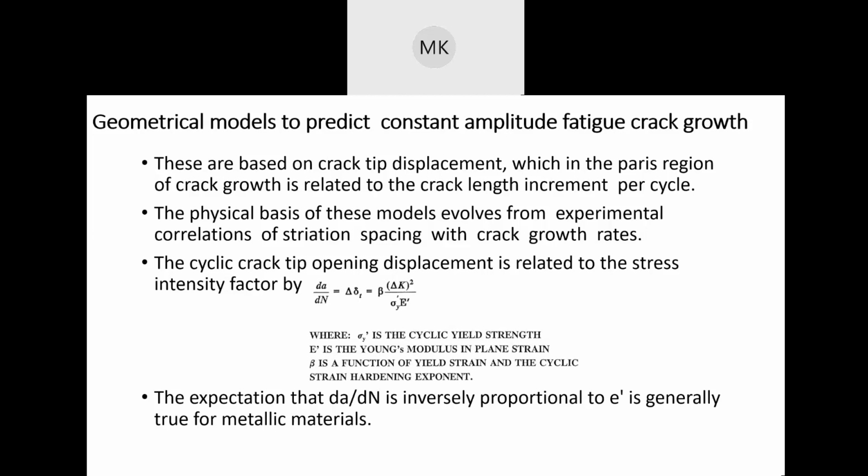The same thing can be done for the crack tip by having the CTOD extensometer, which is a crack tip opening displacement extensometer. It's spring loaded, and you put it between two notches. Once the sample moves, the spring loaded system releases the energy because of the stress between the two springs, and that can give you the displacement happening every time you cycle it. Understanding that crack tip displacement, and the rate at which it changes, can give you an understanding of how and when the material turns from a good material to a bad material at that point. It makes you understand a lot of different things. This is the best experimental way you can do it.